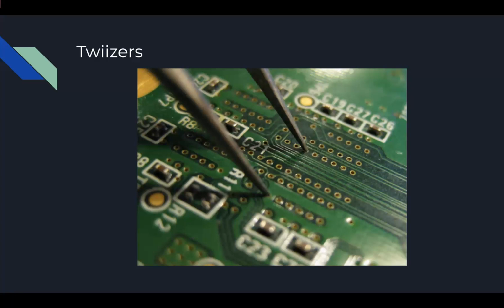But the confusing thing about the Wii is that it actually had 2 processors in it. One processor, called Broadway, was the actual CPU that does the Wii computations. But inside of that chip, they had another processor that was ARM-based and would run all of their security operations, and that is where secrets are being stored. The kicker here is that they all use the same memory. So if you're able to get a memory dump, then maybe those secrets were being stored somewhere. They tried to do this in GameCube mode, but they couldn't access that part of the memory because they didn't need to be able to, and Nintendo had thought of that.